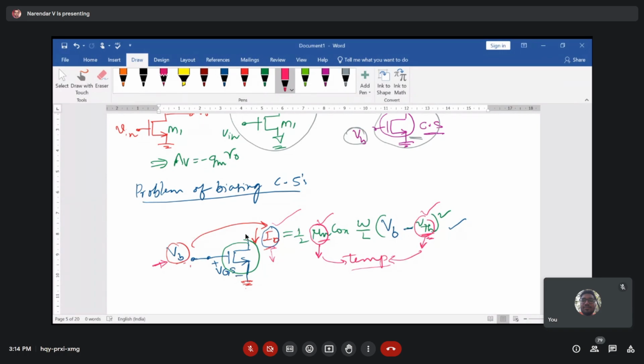When there is a variation in temperature, definitely there is a variation in current, because the device is made up of material which is sensitive to temperature. Right? So definitely mu n is not going to be fixed. Mu n changes as temperature changes, because you are using the same device, let's say a mobile phone, in your home, and then you are going outside, and the temperature varies. As temperature varies, the constant current in the integrated circuit in your mobile phone is going to vary. It is not constant.